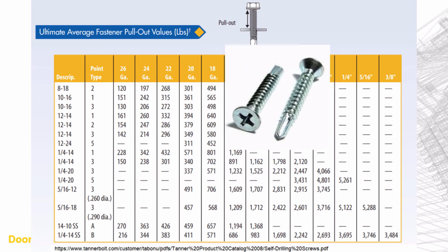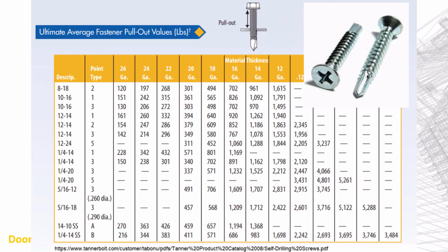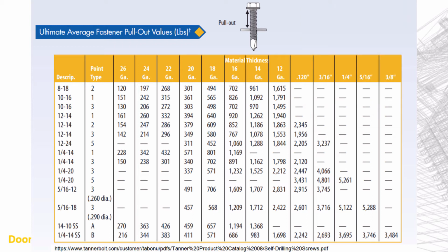Achieving the pull-out strength listed in the table critically requires that the hole which is drilled for the fastener be tight to the threads on the screw. And of course, the pull-out strength changes entirely once you remove the screw and put the screw back in the same hole.